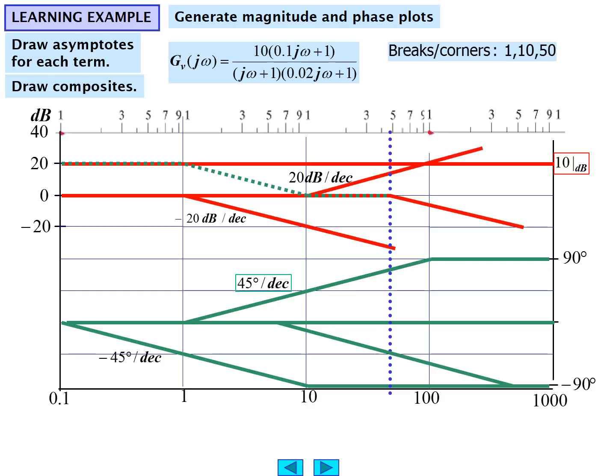So the dotted green line now stays at 0 dB as a result until it hits the next corner or break frequency, which is at 50. And at that point, we no longer have the plus 20 dB per decade canceling out the minus 20 dB per decade, but we've picked up another minus 20 dB per decade, so basically it just follows that particular asymptotic result. So the dotted green line is the resultant for the magnitude by taking the different break frequency asymptotic values into account.